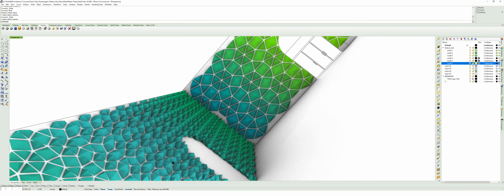Now I'm able to get this plane, which is this plane here. There's a bunch of different things for that, but the main reason I want it is to input that as the plane I offset from. So plugging that into my PL, you can see right away, if I just undo that and redo that, you can see we're flipping everything to be consistent because we have our plane consistently going with Y up and X to the right. Okay, so now I'm going to hide it because it's a little bit distracting.